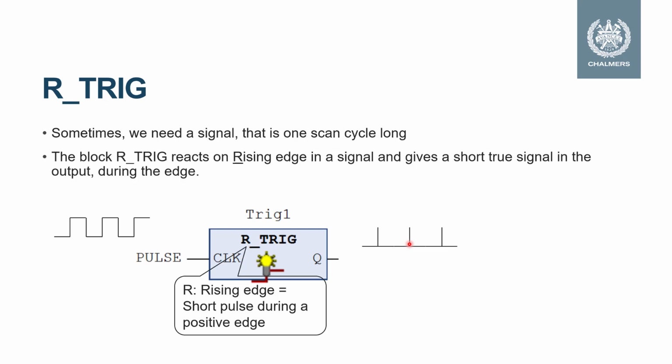In order to achieve this, the block needs to have a memory, which means that it needs a name. We can see that here. The name of the instance allocates memory for the block to use. One word of advice: if you're using more than one trigger block, remember not to give them the same name, because then they will become the same block, as they are occupying the same area in the memory.